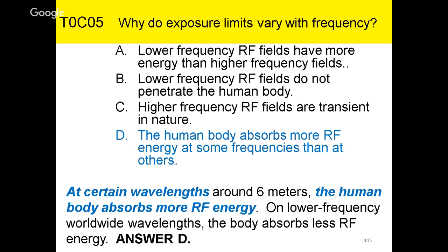This piggybacks a little on concerns people have when using cell phones, because cell phones are basically a full duplex two-way radio. They do emit an RF signal, and they're way higher in frequency than 6 meters is. So the human body might have a little bit more of a tendency to absorb that RF energy and cause issues.